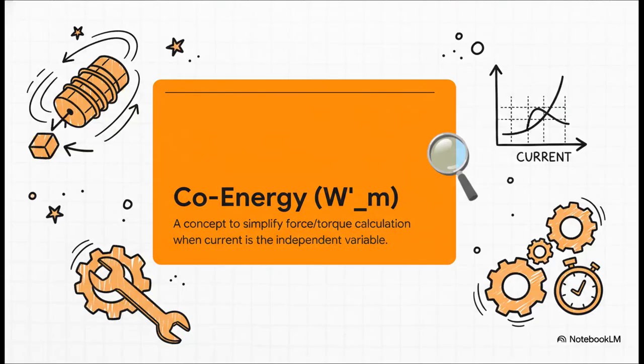So what is this thing exactly? Well, co-energy is a mathematical concept. It's purpose-built to make calculating force simple and practical, especially for those real-world situations where, you guessed it, current is the thing you're actually controlling. Now, it's not a physical energy you can go out and measure with a meter, but think of it as a super powerful analytical shortcut.